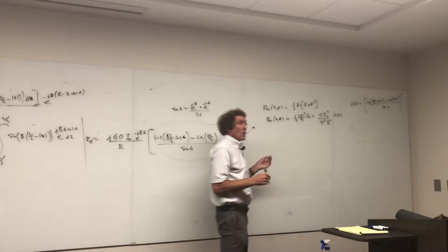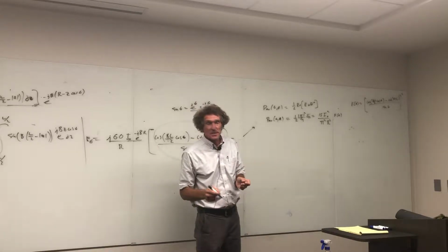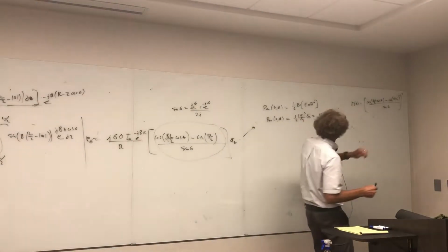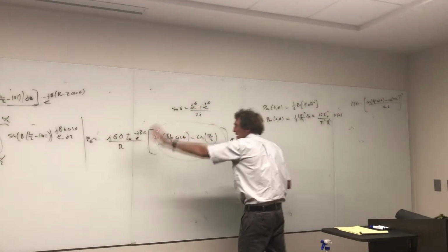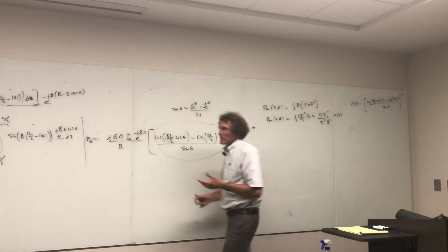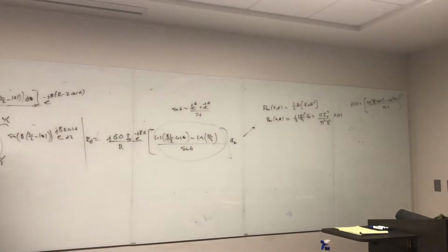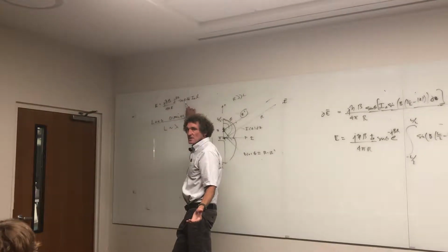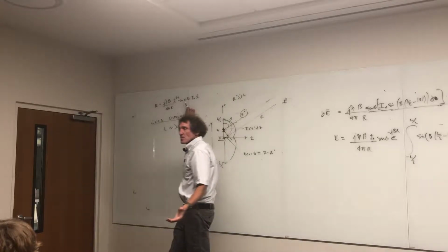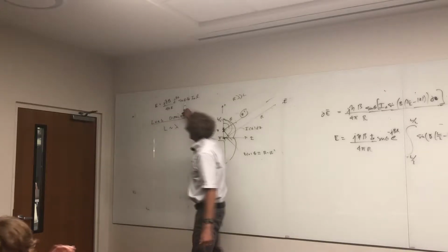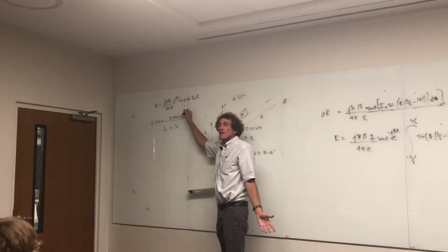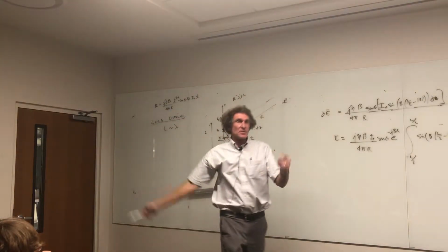Now, what is important to understand is this function right here. Before, when we thought about the short dipole, if I got the power pattern, I'm basically squaring the E field, right? You all see how that sine squared would appear here for the power density? So when you do the normalized power density for this one, it's just sine squared, right? Everybody see that? Here's the danger.